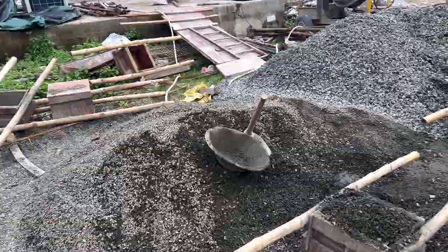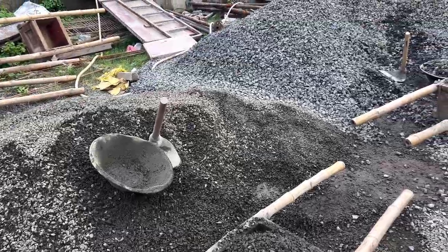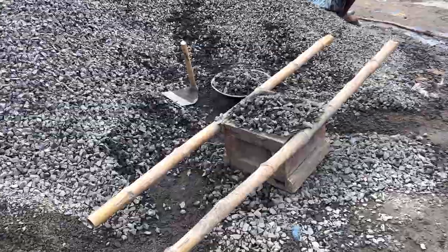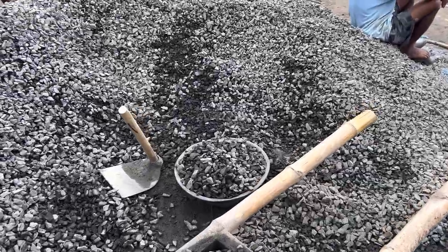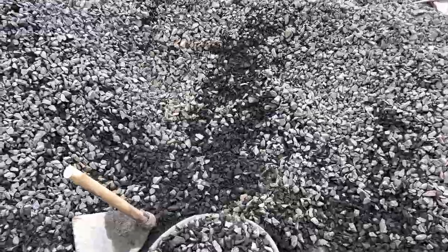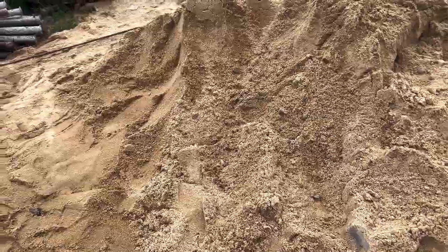In the moist condition, if we take 1200 kg, we are not getting exactly 1200 kgs of aggregate because there is some wet water in it. So, we are getting less coarse aggregate and more water. So, the mix ratio will be a problem.